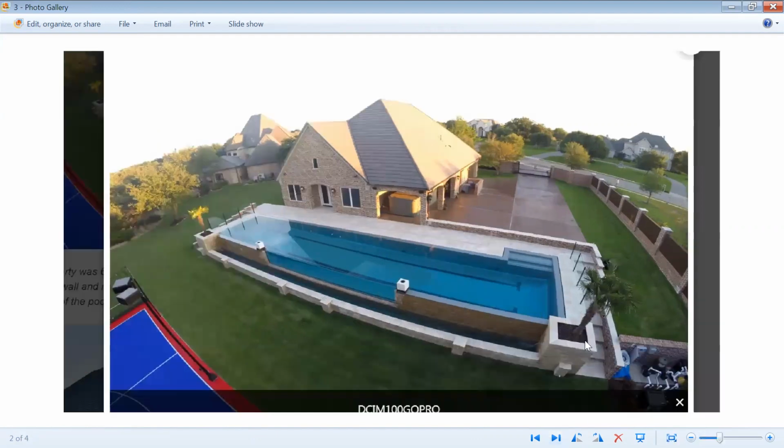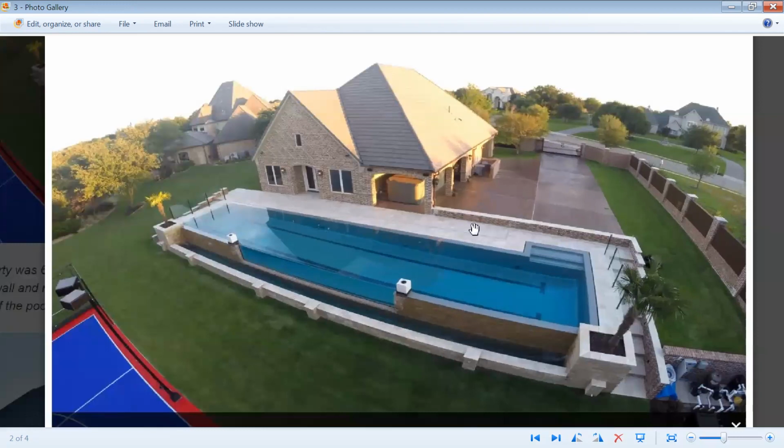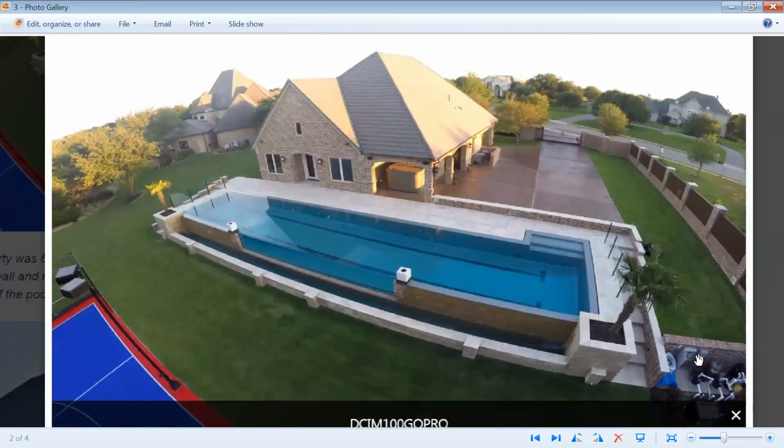Now, if you notice here, and I'm going to divert briefly, notice where he puts the pool equipment. It's always going to be down toward the lower side of the pool and not the upper side. The reason for that is it's going to be better performance if the pool equipment is lower, because it's going to be very easy to prime any of these pumps. But any pumps that are up on the higher level and maybe much further back will be very difficult to prime. Not impossible, but more difficult to prime.